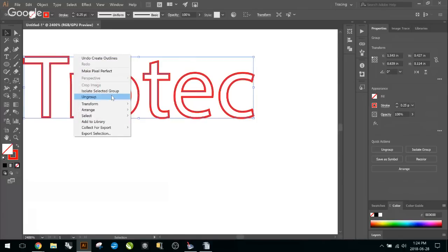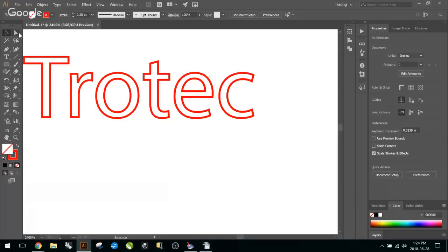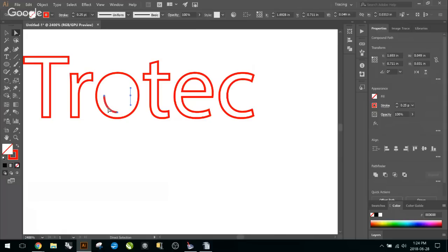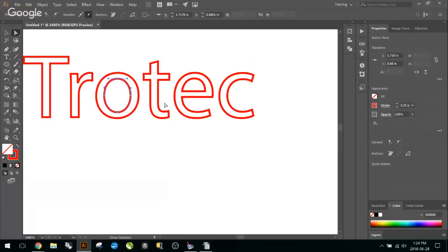If you right-click again and press ungroup, it has broken all the lines into their own strokes. So now with our direct selection tool, we can click on our line, and we can delete it. I think that's what the question was. I hope that answers it.